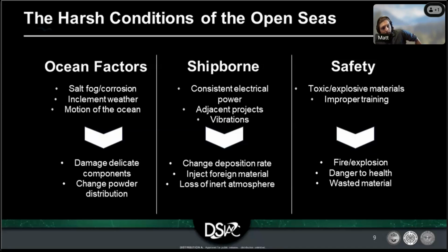So some of the big things, especially when I was with the Navy, we heard quite a bit about salt fog and corrosion, kind of the bane of a lot of the systems out there. If you don't know what salt fog is, it's where the salty sea gets atomized and will deposit on ships and aircraft and stuff like that, and it will corrode. Combined with the high humidity, it will corrode things a lot quicker than normally anticipated.